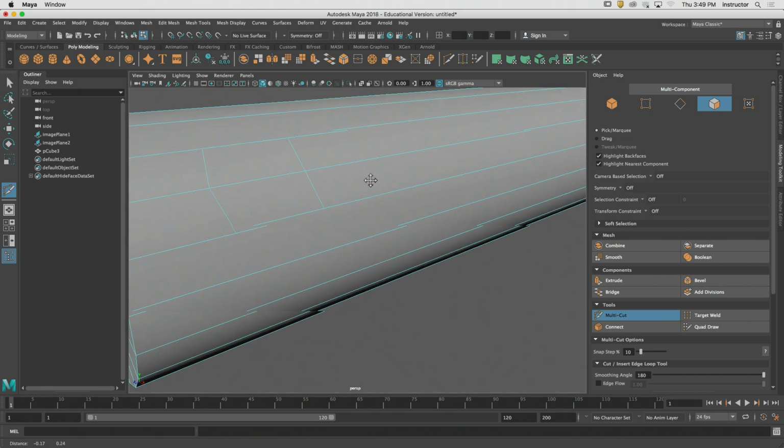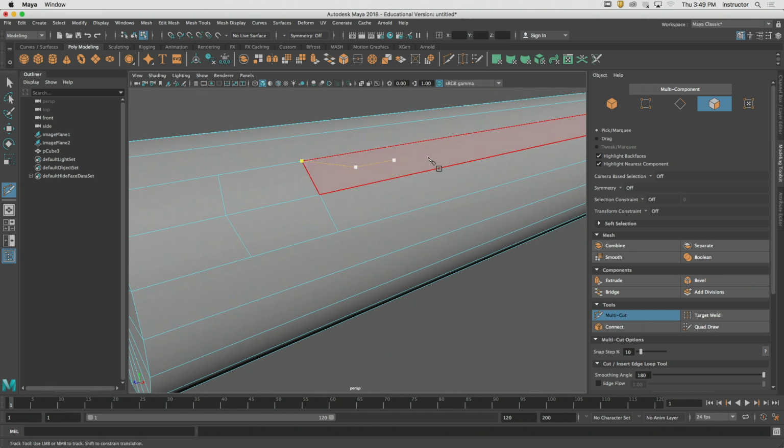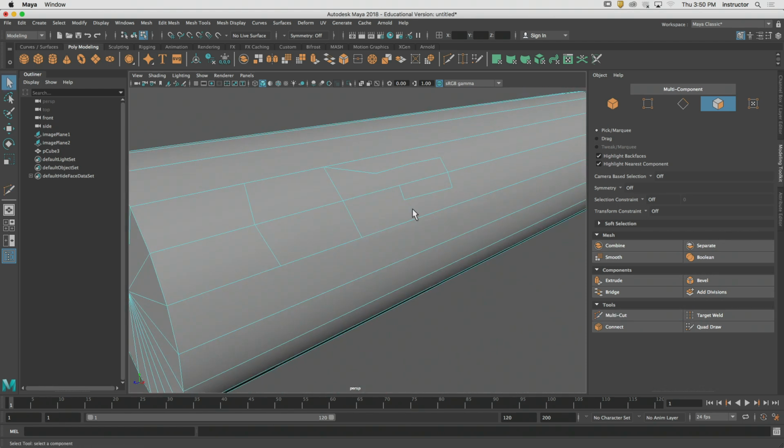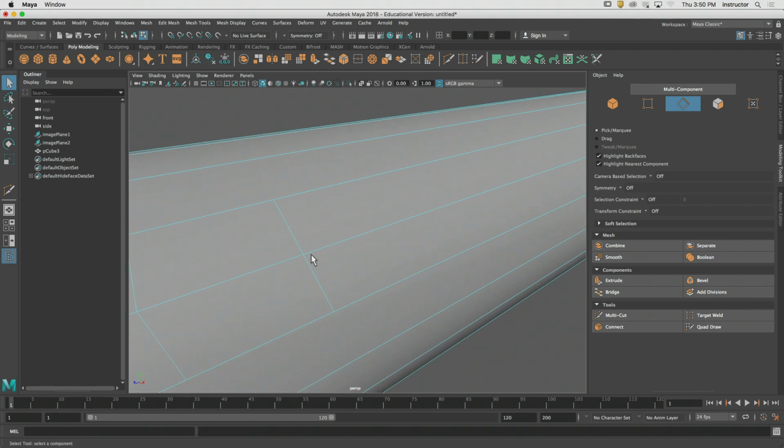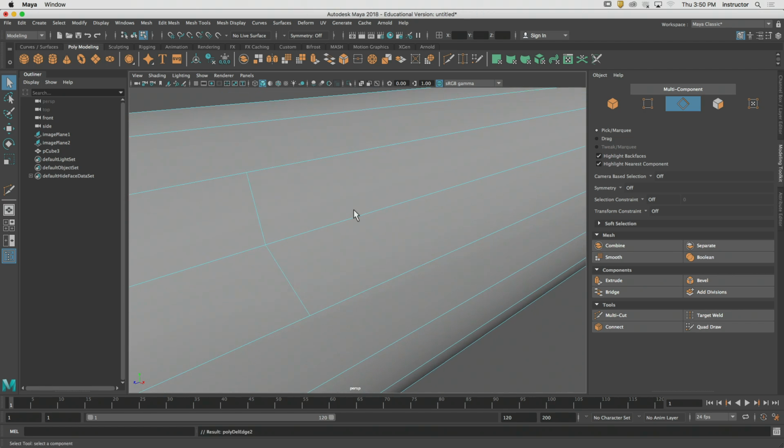You can start on the interior like this, but you're kind of getting into some bad form and bad practice there. These floating edges are going to cause massive problems inside of our entire sequence. So we want to try to avoid placing edges that aren't connected to an existing edge span. That's going to cause some problems.